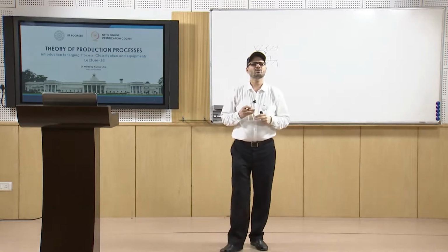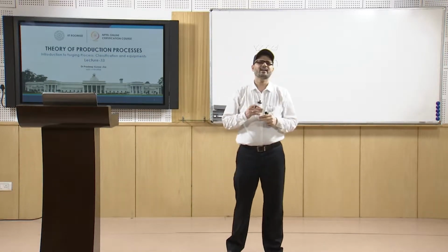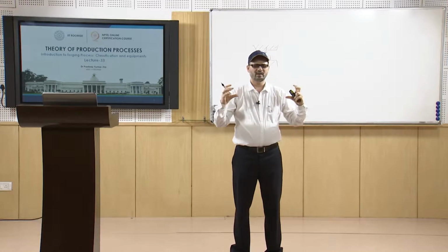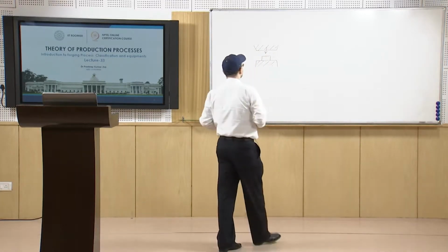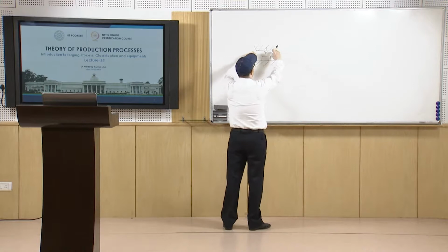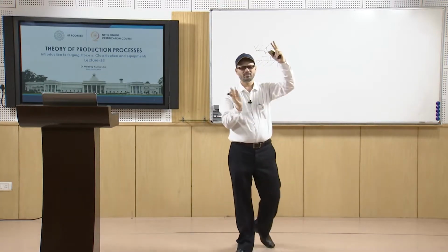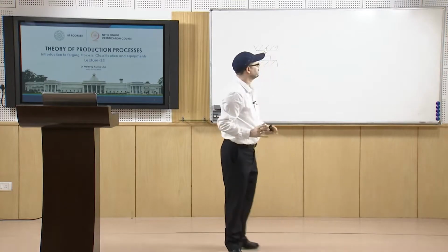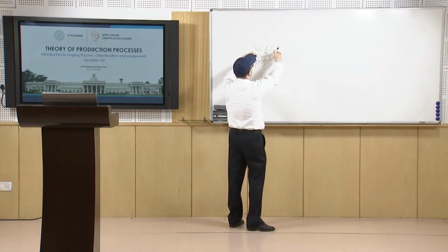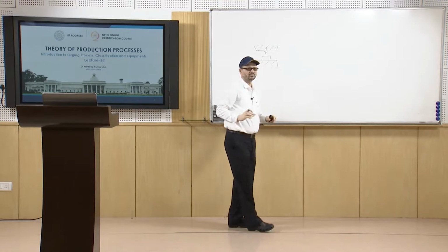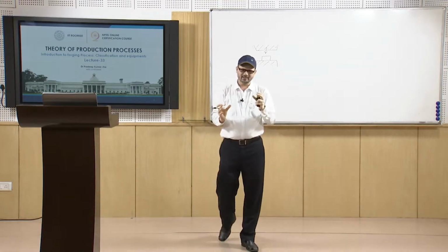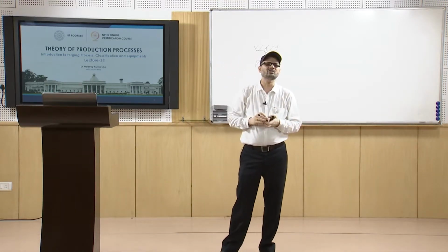When we talk about closed die forging, the dies get closed. When the die comes and starts touching, there is a gap, but slowly when the two dies meet, they are closed from both ends, and in the die you have impressions made.